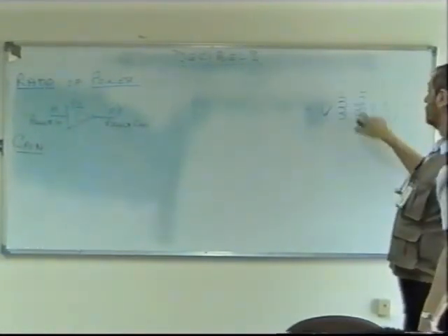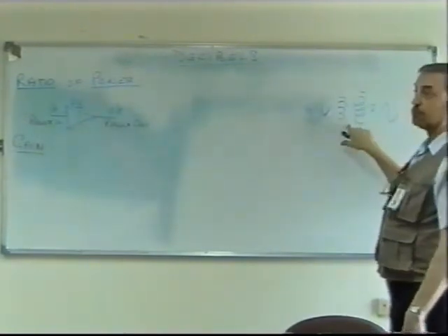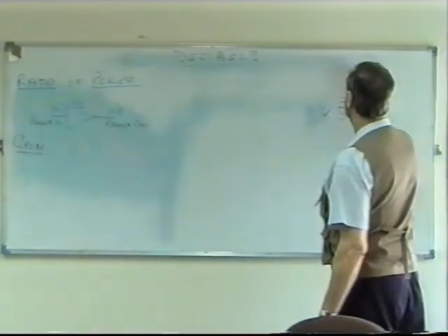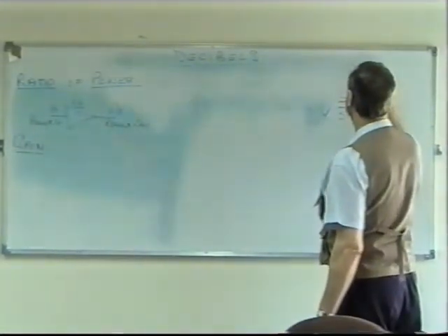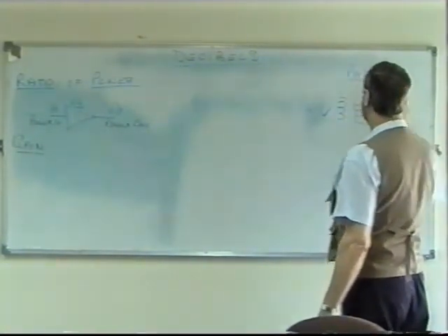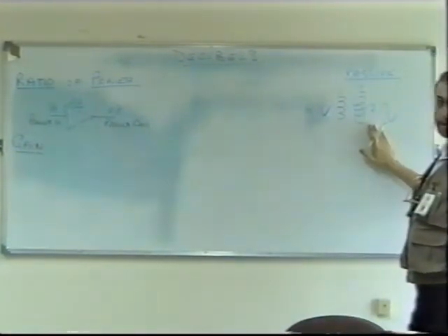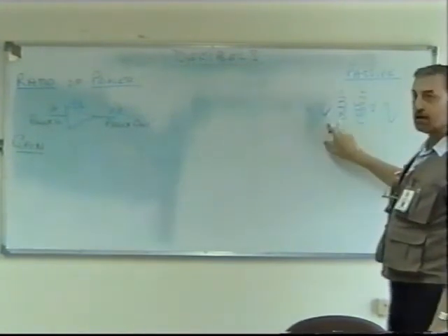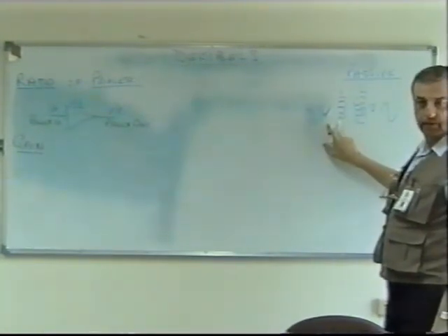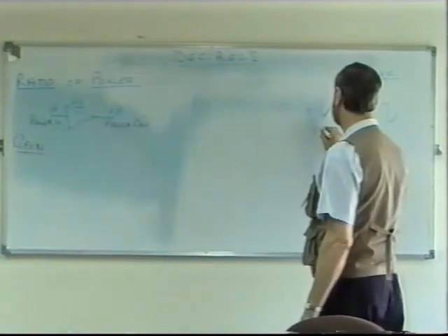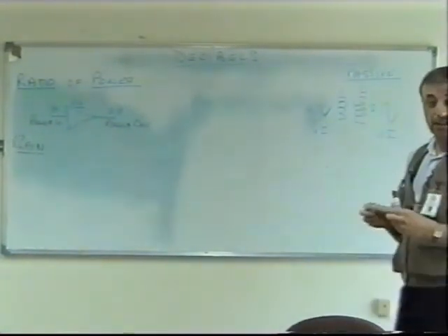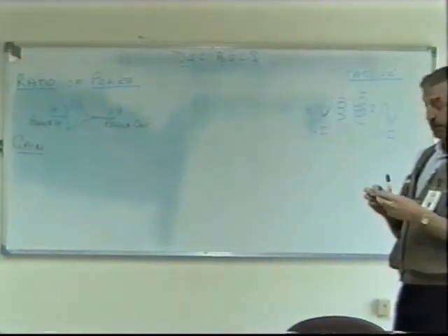But we must understand that a transformer is a passive device, isn't it? And that's really what we're talking about here. Because it's passive, no power is being added, so we know that the current at the output must be half the current at the input. Because VI is power input, isn't it? It must equal the VI output, apart from a little loss in the transformer itself.